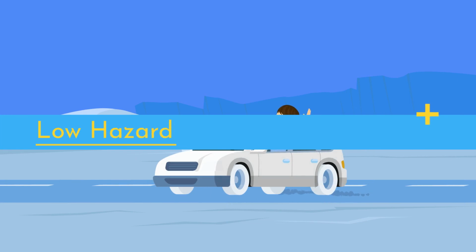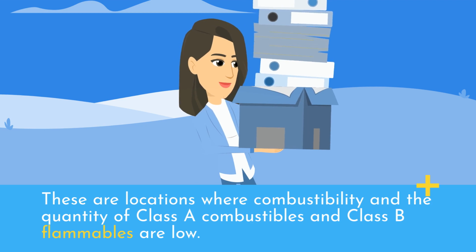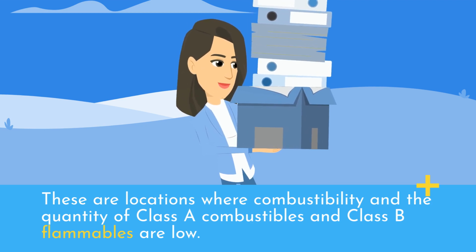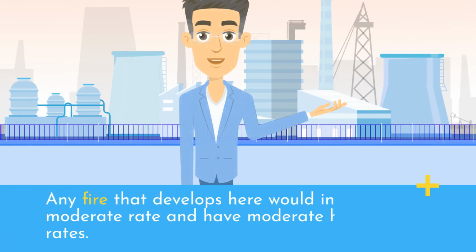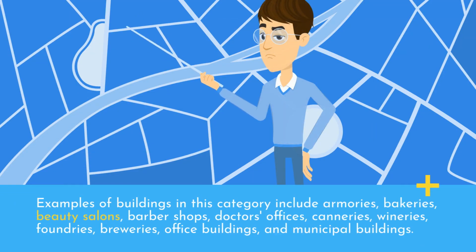Low hazard. These are locations where combustibility and the quantity of Class A combustibles and Class B flammables are low. Any fire that develops here would increase at a moderate rate and have moderate heat release rates. Examples of buildings in this category include armories, bakeries, beauty salons, barber shops, doctors' offices, canneries, wineries, foundries, breweries, office buildings, and municipal buildings.